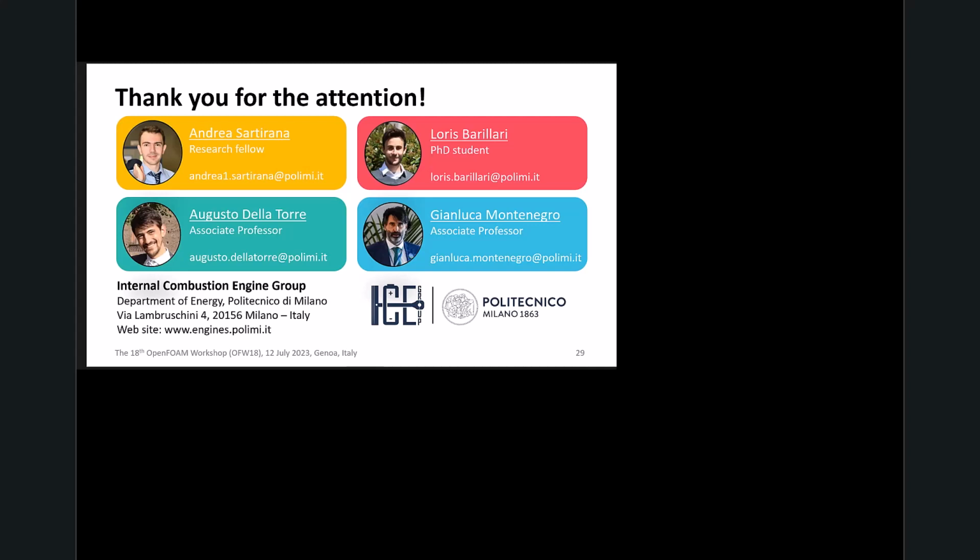Yeah, but my question was more like, can you also use the 3D CFD model and implement a reduced order model, instead of solving the 3D system? No, this methodology also works with 1D models. For example, for the calculation of the chemical reaction kinetics, we start from a 1D model, in which we have a discretization only on the x-axis. In this way the simulation time is low. For example, we go from a simulation that requires 1 week to 3 hours, or even less. So there is also this possibility.